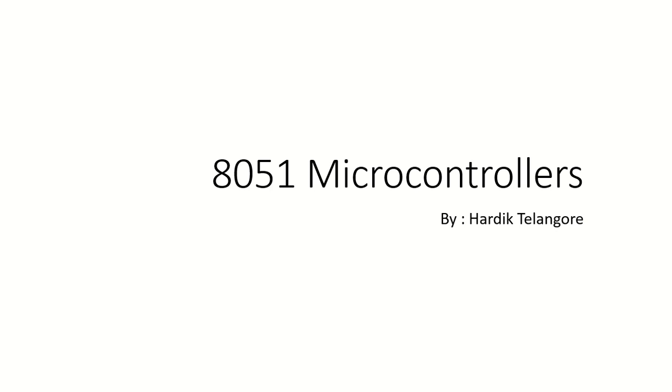We have two 16-bit timers or counters. We have a full duplex serial data transmitter. We have four register banks. We have 64 KB program memory and 64 KB external RAM addressability. We are going to discuss RAM in detail as well in upcoming classes. Then we have the interrupt structure with two priority levels.